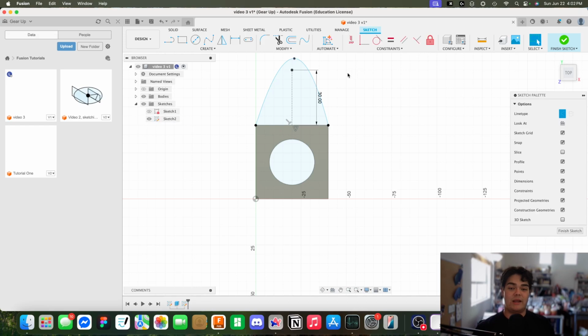Now I'm going to go ahead and anchor this top point to the tip of that line. The way I'm going to do that is using a manual constraint. As you can see, Fusion's created a lot of constraints for me as I'm sketching, but sometimes you want to add an additional constraint to make sure that things like splines, or sometimes even concentric circles, are well defined. So I'm going to use this one. It's coincident, which means 2 points overlapping. I'm going to click on this point, then on this one, and that's going to lock them together. Awesome. My spline is now black, which means it's fully defined, and I now have this new area inside.